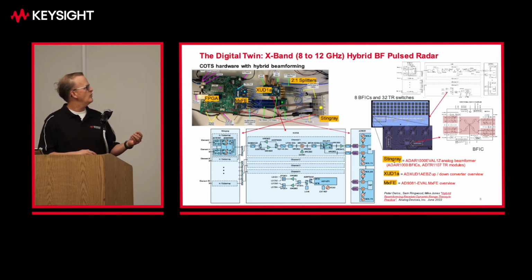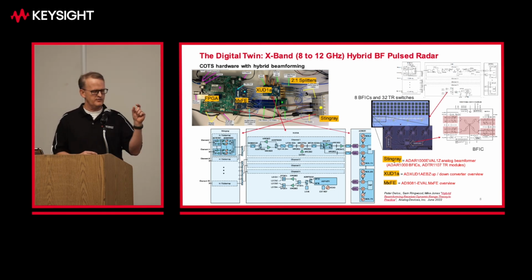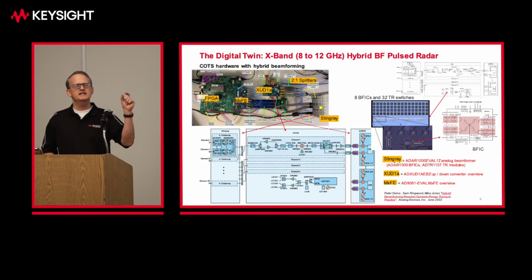And what they did is, this is actually from the ATR 1000 beamformer data sheet. And everything in pink there is a beamformer IC physical path. And they basically took the S parameter, the frequency-dependent data from the data sheet, and just put it right into SystemVue, into the model, the SpectraSys model, the phase array model.